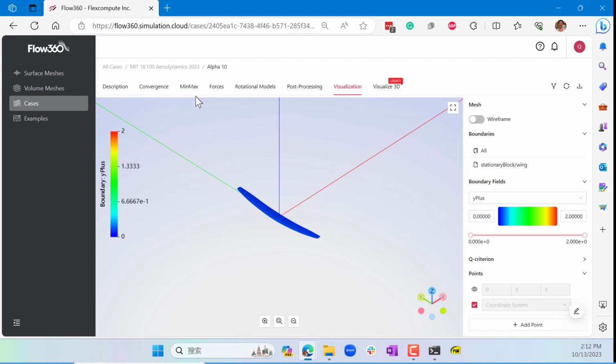So we'll first start by talking about what the simulation is actually doing. A computational fluid dynamics simulation discretizes all the space outside of the airplane, in this case outside of the wing. It discretizes in the sense that it splits the entire space into small control volumes, and it solves a bunch of equations, the conservation of mass, conservation of momentum, conservation of energy, etc., on all